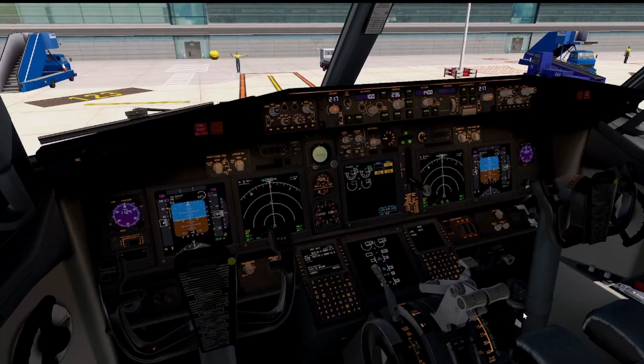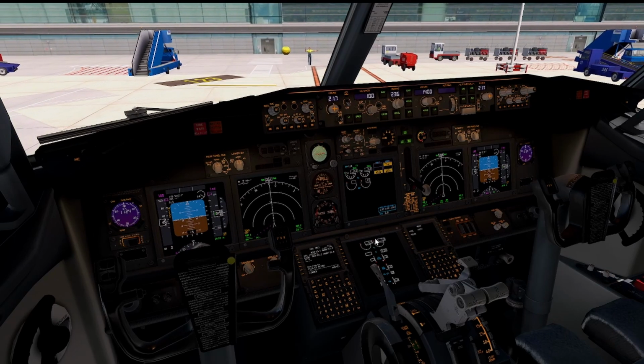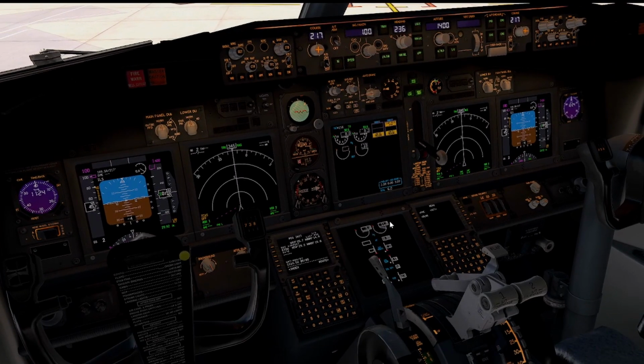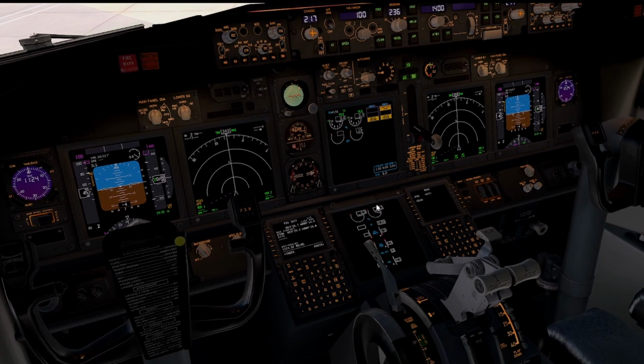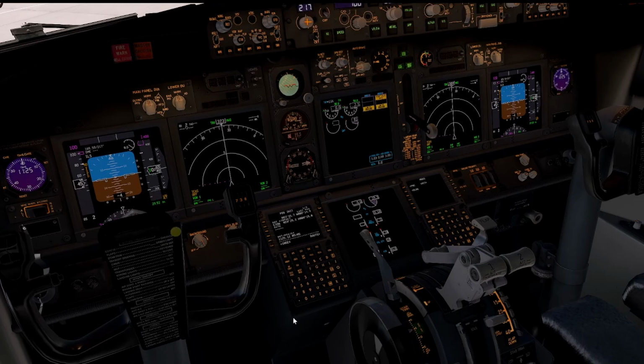Now you can hear the engine slowly roaring up, and then you're gonna look here on your lower engine display. We're gonna wait for about 25% N2 before we introduce fuel. When you hit 25%, we're gonna introduce fuel right here. And now your engine will fire up.